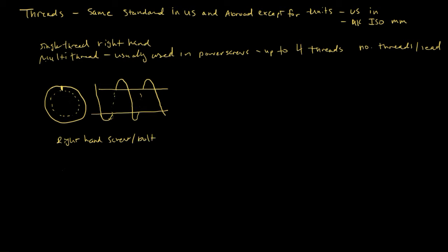And it is single threaded, and it's single threaded because if you look at the lead, and the lead is where the same thread comes to the same position. This is the lead L. You see that there's a single thread in the lead, and in this case the lead is also equal to the pitch of this thread.